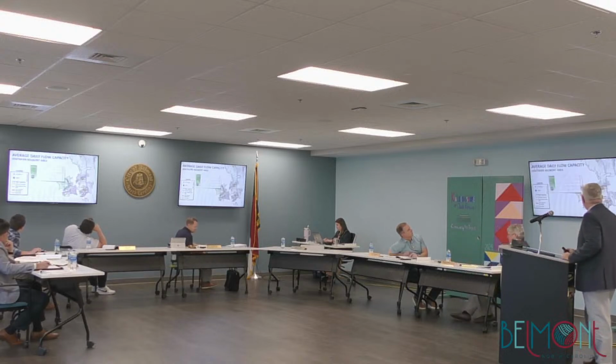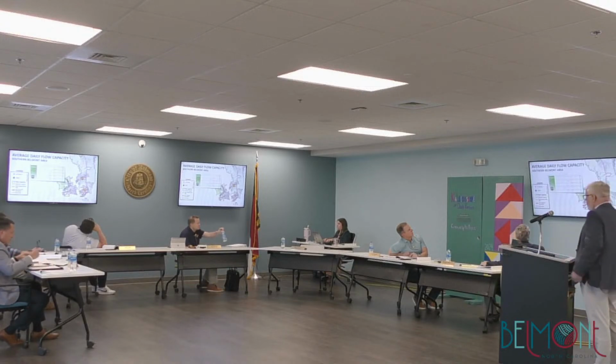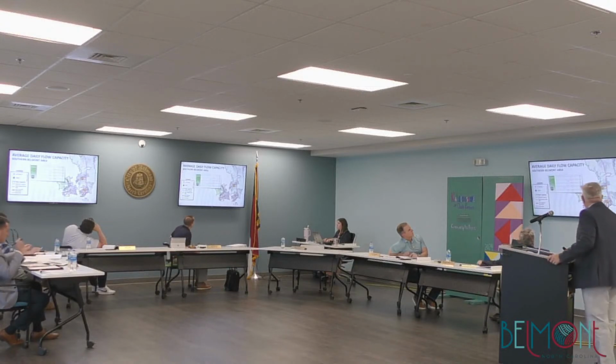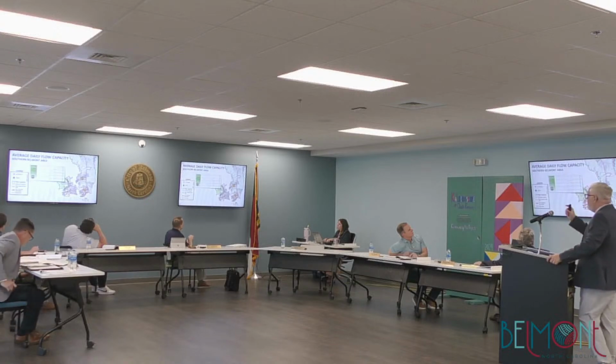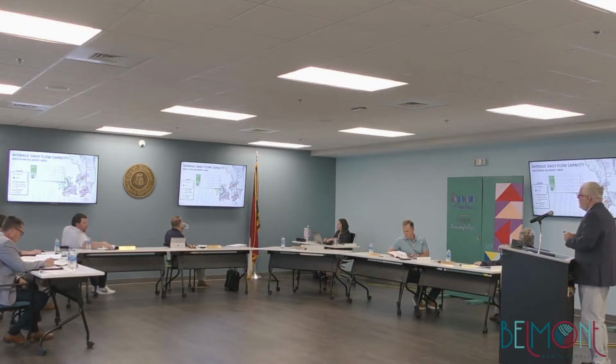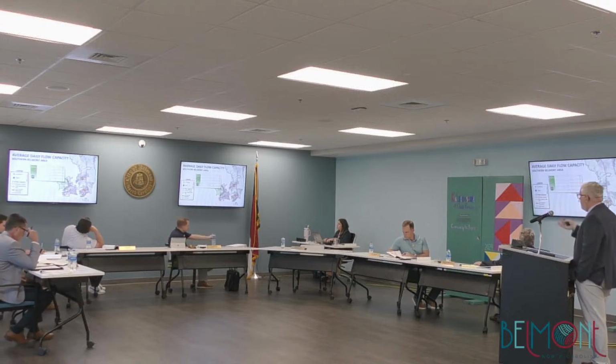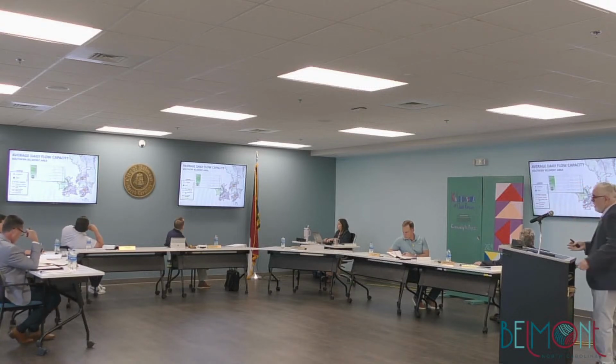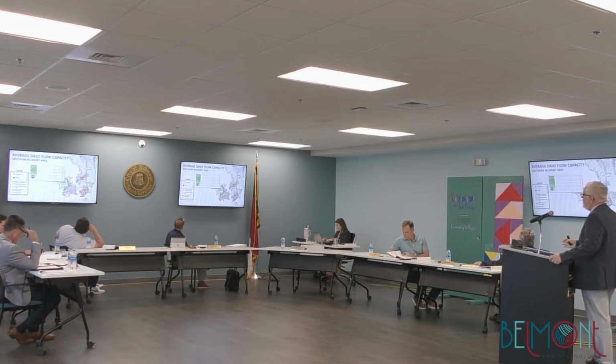They're just a different color to designate that that is a pressure versus the green being gravity. Then we come down to the southern Belmont area, and this is the Morgan's Branch and Reflection Point lift station. I've highlighted those two in particular. I'm going to go just a little bit deep here for a moment. One, there's a screenshot of software called Lift Command that your staff is now using that tracks flow through every lift station. That was part of this project. And you can see how they're daisy chained together.